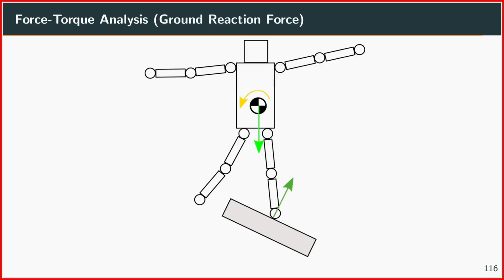And the way we can stabilize this is, of course, that the robot is somehow having different forces, for example, from the ground. Here there might be a ground reaction force where the robot is just standing on something. And then we can project those forces to the center of mass. And if those forces act against the forces of gravity here, then the robot would be stable.